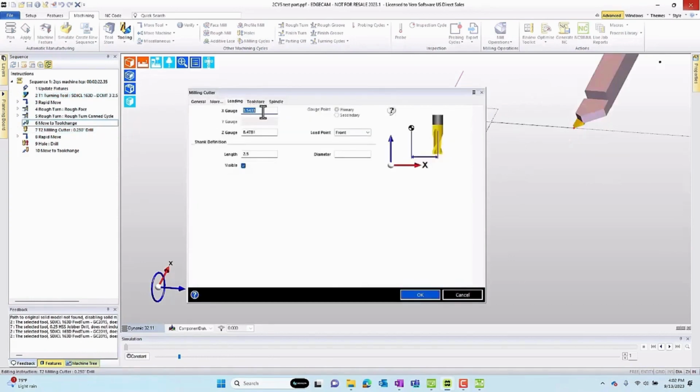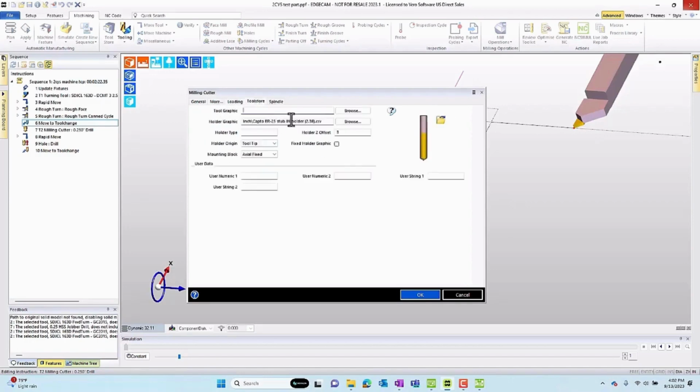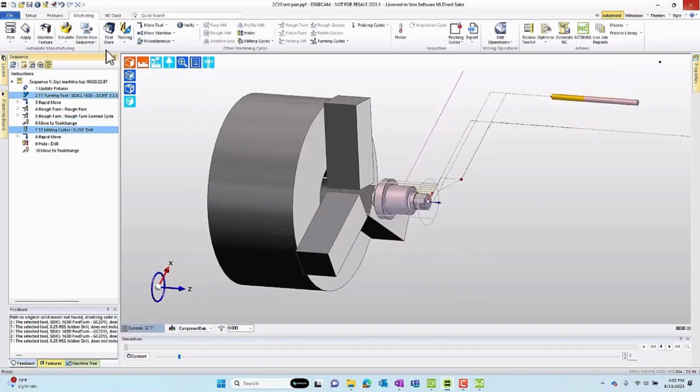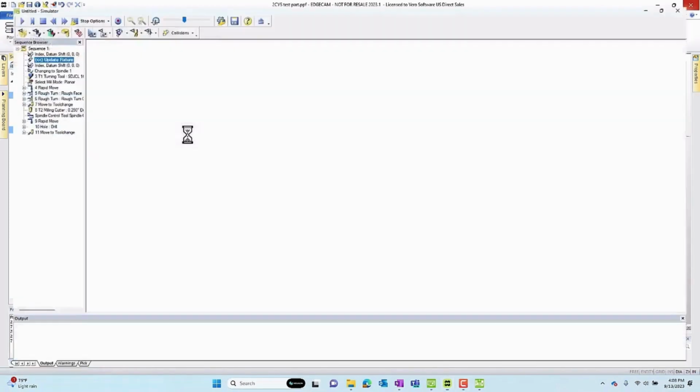On the drill, my X position gets the drill into the center hole in the block. My drill hangs off in Z. So I've got the Z value of the block plus my hang-off distance. And we'll be talking about how to get those values for the block. While we're at it, we'll go ahead and remove the holder that would be appropriate to a mill, but isn't needed in the turning center.